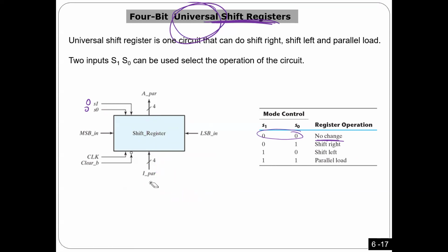Okay. That's why here I need, for sure, a clock. Also I have here 1 bit for clear. So this bit, if you put here 0, you are going to clear all the flip flops you have here. On top of that, I need also serial in to the right, serial in to the left. One to the right, one to the left.